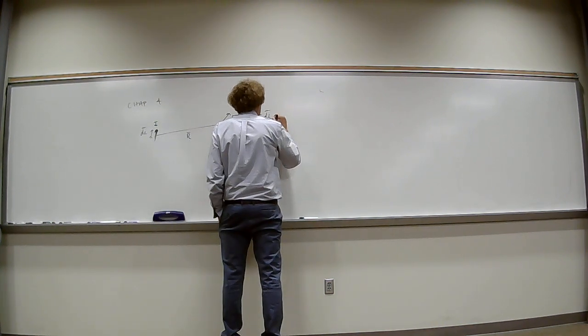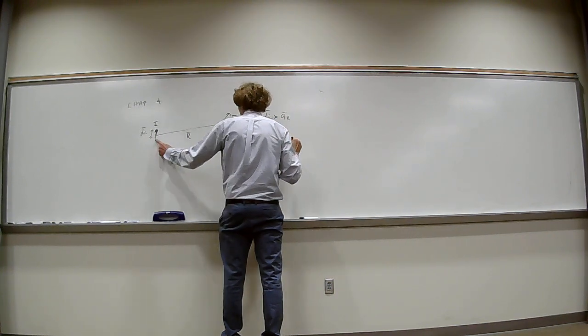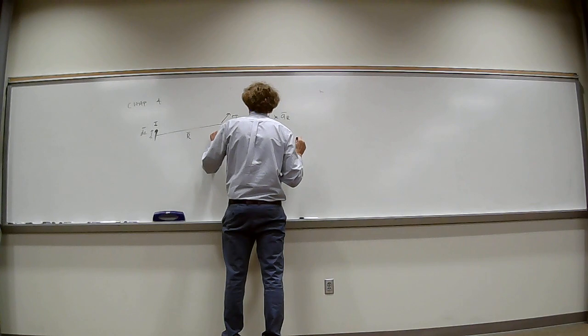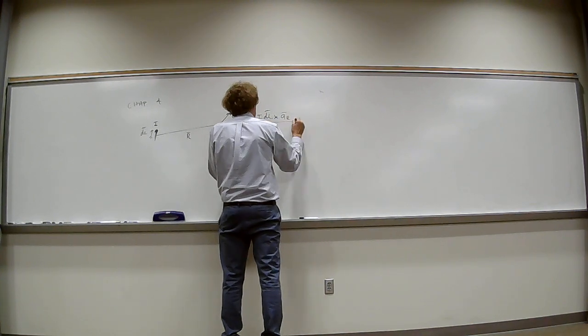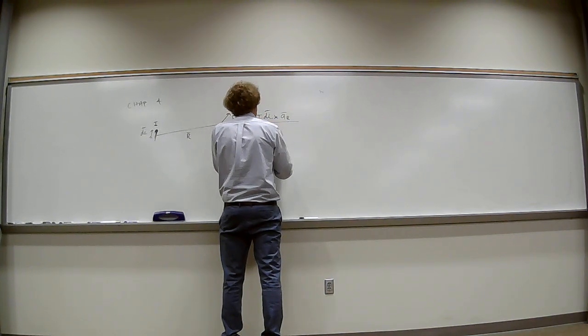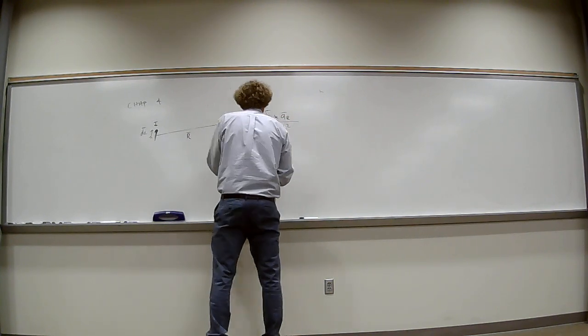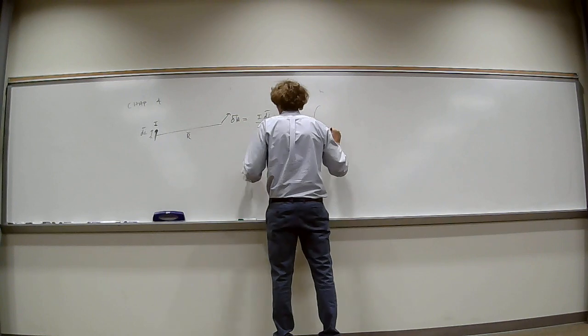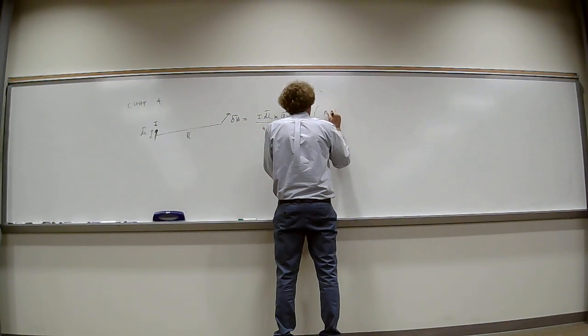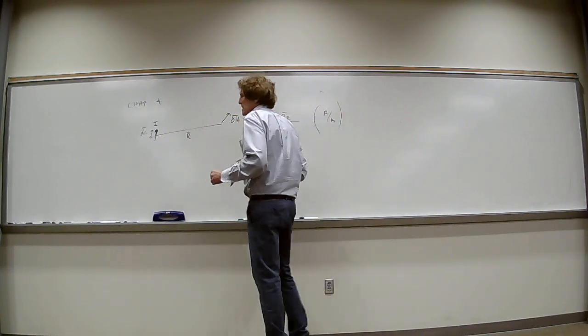Then it's going to be crossed into a unit vector, aR, that goes from the actual source to the point of observation of the H field. And it's over 4 pi, and then it's going to be magnitude of R squared. Now he's going to show you that the units of the differential H field will be amps per meter.